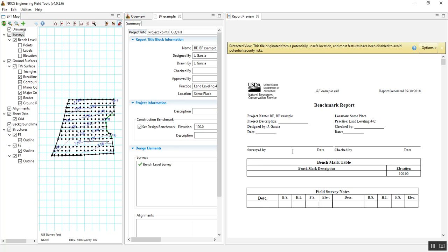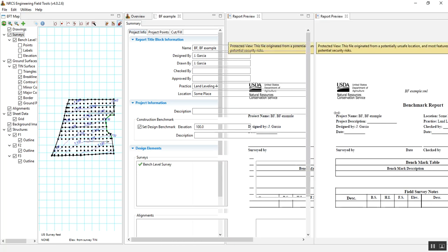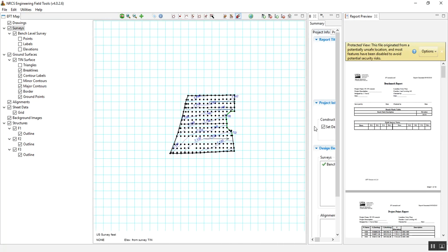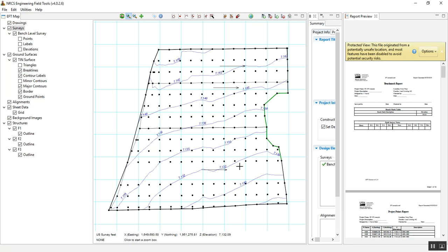And we want to minimize the cuts in some places because you don't want to make the producer's field not as productive by cutting too much. Therefore, that's why it's important, if you have such big cuts and you're going to have to do it, to go out there and bore some holes and see what kind of material you're going to hit, and if need be, save the top 1 foot, place it somewhere else, place it on the field adjacent to it, level it, and then bring back that field and put it back on the field so that they have good topsoil.